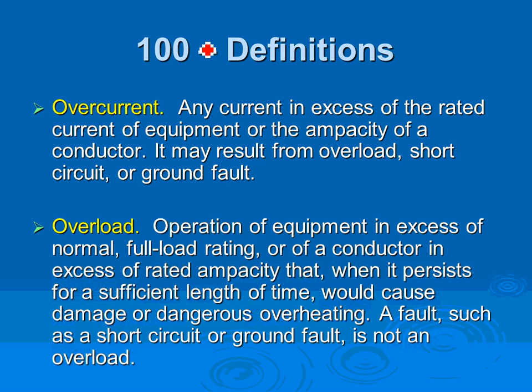So when it comes to feeders, the circuit breaker and fuse protect you from overcurrent, protection device in all cases except when it comes to machines that have motors. That's what you guys covered with my friend Jeff Belgic yesterday. When it comes to motors, because of the windings and the magnet wire that they use inside them, and because they're so expensive, more expensive than a lighting fixture like this, right?